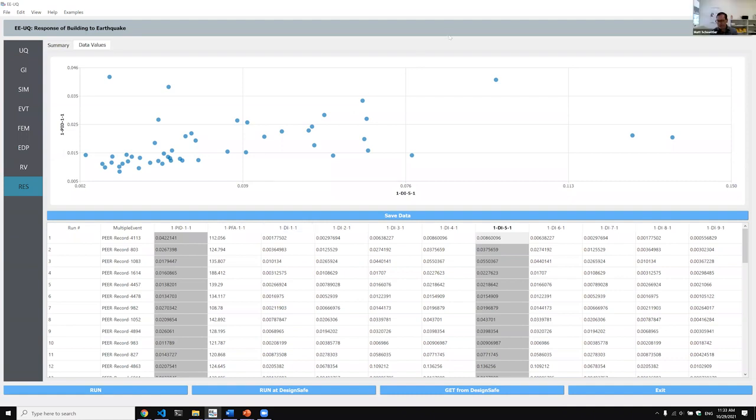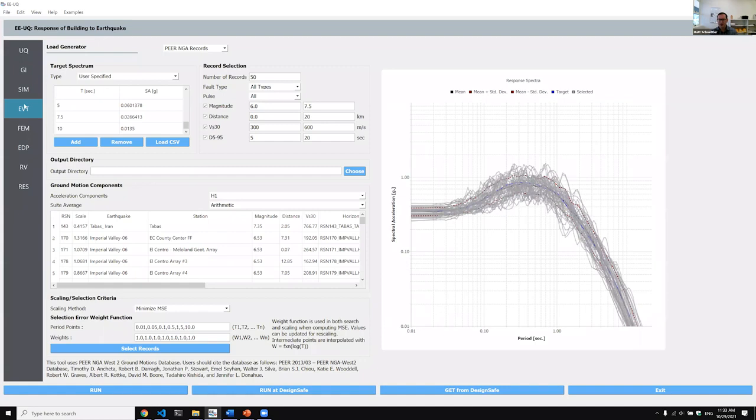And you're providing parameters to the ground motion selection. Could you just recap the scaling process, how those records that do get selected are scaled? Yeah, so the ground motion scaling is done by the NGA-West2 website, and the scaling is designed to minimize the mean squared error in our selection.